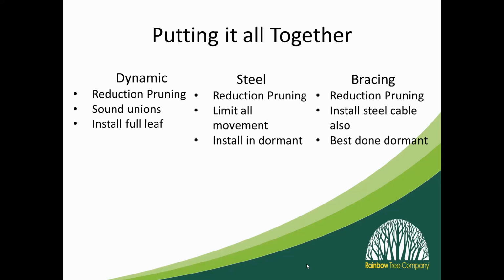Going back to that one big picture, we had that huge crack in there. That would be bolting, if we had large enough tools to do that, and I'll get into that in a couple slides. Decay is another double-edged sword. If you have decay in there, it's always going to continue, and maybe that butt's going to fall off. Having a brace section above to hold that butt in position might be a good opportunity, but then decay is going to run down the bolt itself.